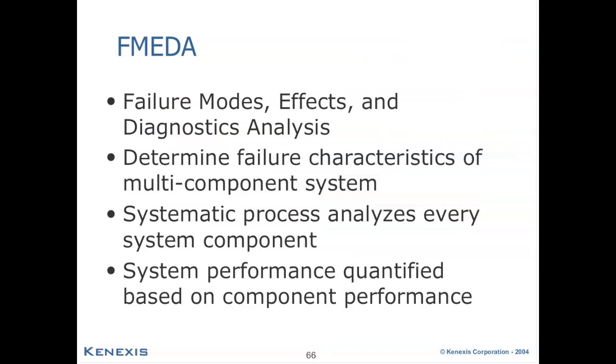You can also use the FMEDA, or Failure Modes, Effects, and Diagnostics Analysis, as a means to determine the failure characteristics of multiple components. In this manner, you would go ahead and systematically analyze every system component and quantify the performance of your system based on the quality of your components.